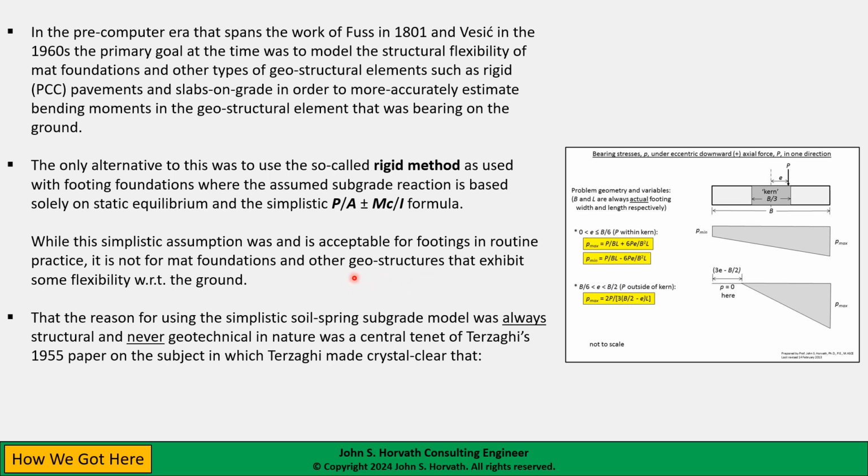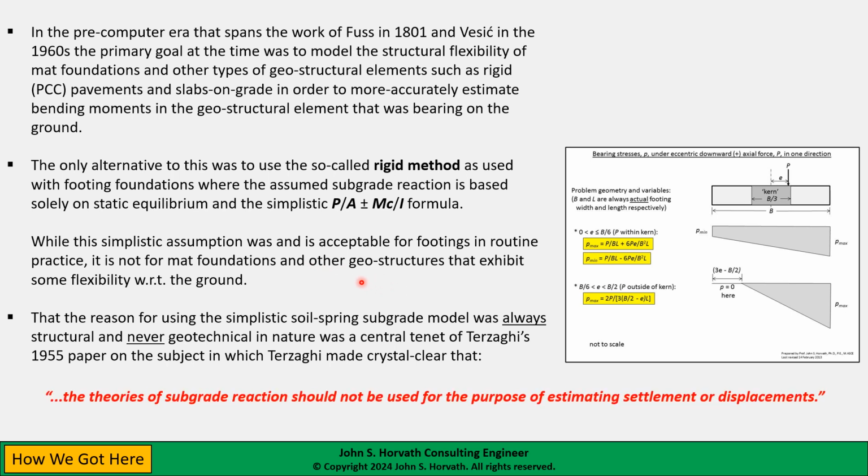And again, the fact that the simple soil spring subgrade model was always structural in nature, never geotechnical in nature, was a central tenet of Terzaghi's 1955 paper. And I think Terzaghi made it crystal clear. It's worth repeating again, this is a quote directly from his paper: The theories of subgrade reaction, that is, using the independent soil spring model with constant values of K, should not be used for the purpose of estimating settlements or displacement.